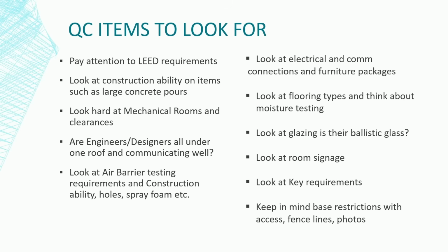Keep in mind base restrictions with access, fence lines, and photos. This is where you're going to make your O-face, and I know I'm going to really surprise you folks. Designers don't typically like to get out from behind their desk and come to site and do inspections. And if you're on a base where you can take photos, yay! Then you can take those photos, keep them up to date, be that bridge for them. But if you're not, you're going to really need to facilitate those site inspections, and you need to pay attention to how many site inspections the design team has got figured in, and at what point, what percentage of completion they want to come out.